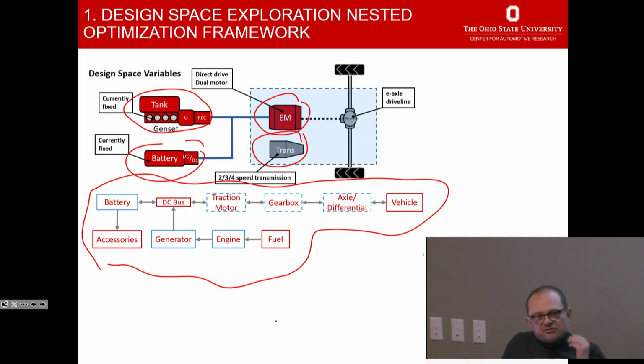Well, one of the things that has changed is that our simulator is much, much more sophisticated, much closer to the reality of what the vehicle does. And a lot of the simulator development involved a year of work with Cummins and Freightliner custom chassis to validate it against experimental data. In fact, we did experiments on the heavy-duty chassis dynamometer at CAR to actually create a database for the conventional vehicle so that we could validate our conventional vehicle simulator against data collected from the conventional vehicle.